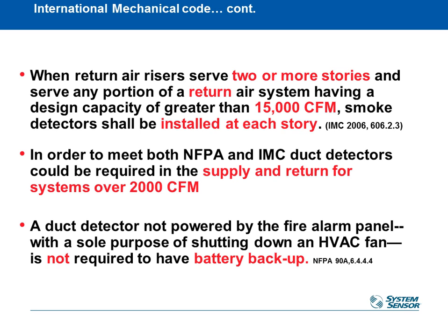The standard of care is either one of these 2 codes that requires you to put a duct detector in at 2,000 CFM. So even if no one's forcing you to do it, you probably should design your building that way, or you're going to be the one that's liable later when there's a problem. Because the standard of care is to do it, even if the fire department doesn't force your hand to do it.